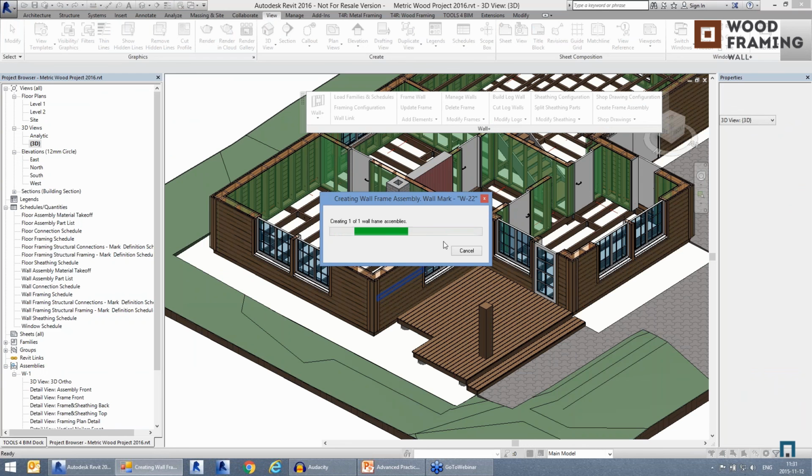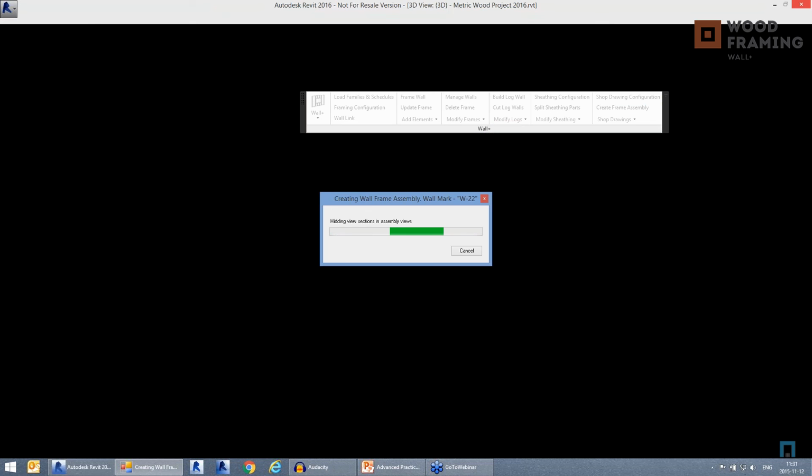So let's do that for this wall segment. Yes, and now the tool makes the same things. It makes the assembly, it collects everything from this wall segment. It automatically adds dimensions, assigns the graphical presentment, adds tags automatically, and renumbers elements automatically. Then the tool makes schedules, and the tool now adds views into the sheet according to my previous one.